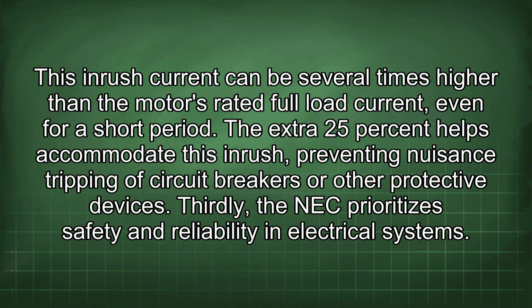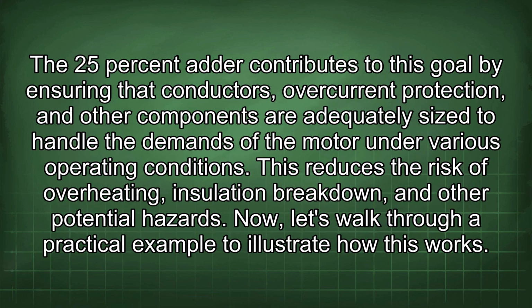Thirdly, the NEC prioritizes safety and reliability in electrical systems. The 25% adder contributes to this goal by ensuring that conductors, overcurrent protection, and other components are adequately sized to handle the demands of the motor under various operating conditions. This reduces the risk of overheating, insulation breakdown, and other potential hazards.